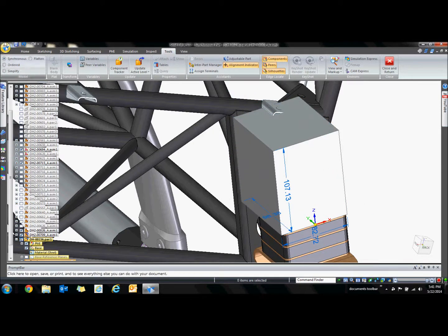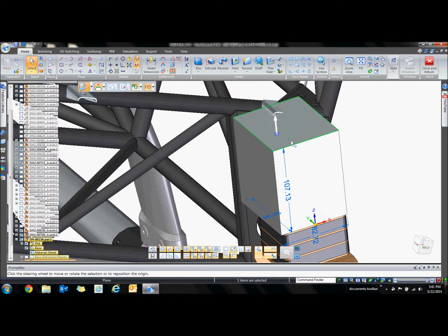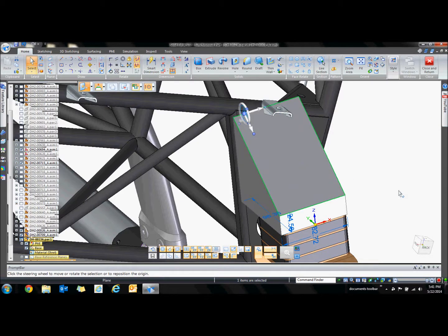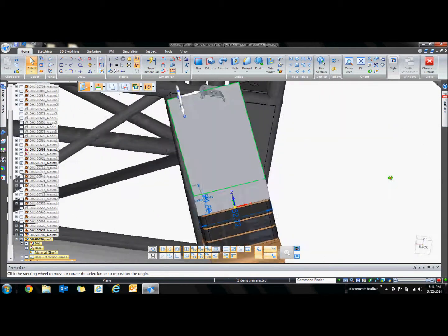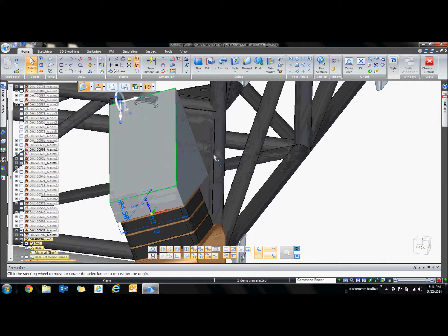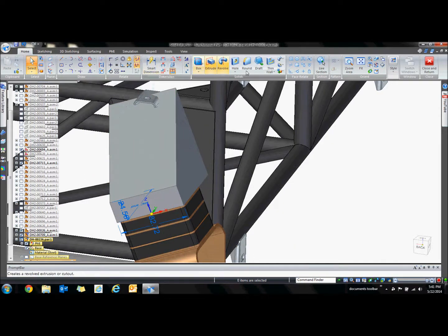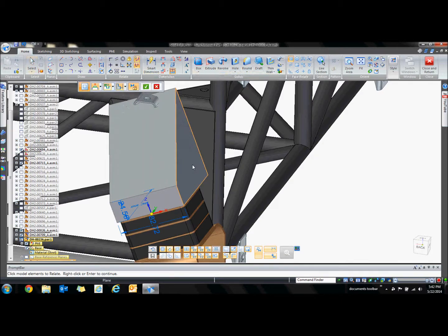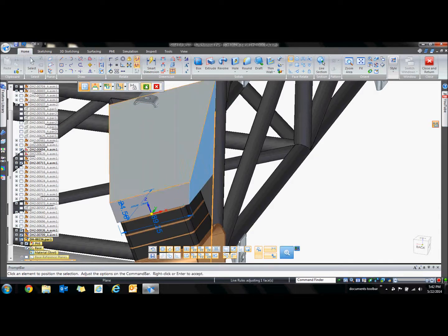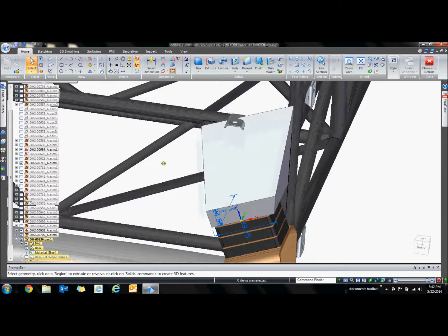That looks awesome. So using our synchronous commands, I'm going to go ahead and put some shape to this block, because it can't just be like this. And he needs to go down about, I think he should be around 40 degrees. That looks pretty good. Well, oh, you know what? On the other side, this guy right here has to match up so he can be welded correctly. Let me go ahead and deselect him, and I know that I need to do a coincidental relationship, or I should say a coplanar relationship, between this face and this face. And sure enough, it happens just as we planned it. From here, I'd like to do a little bit of drawing, or I should say I'm going to do a project to sketch.